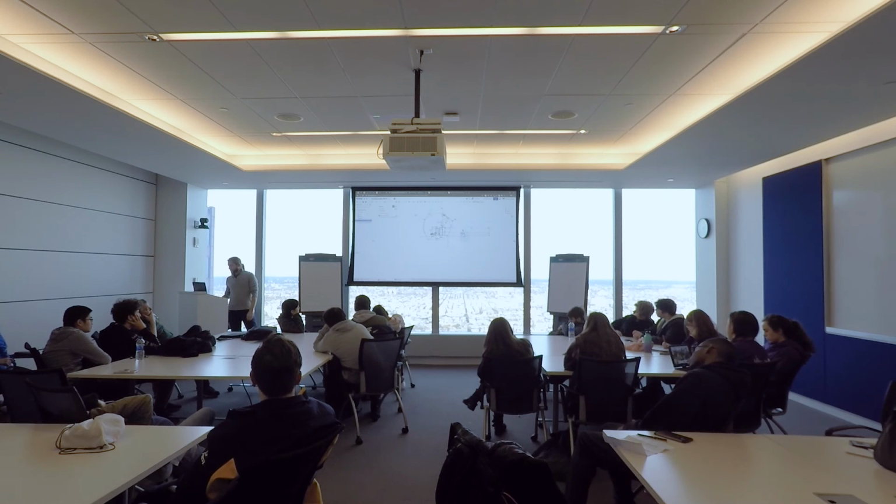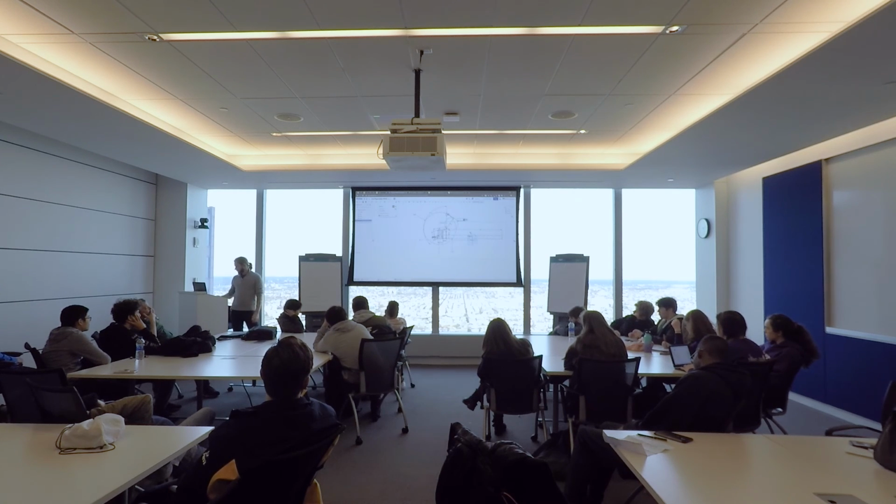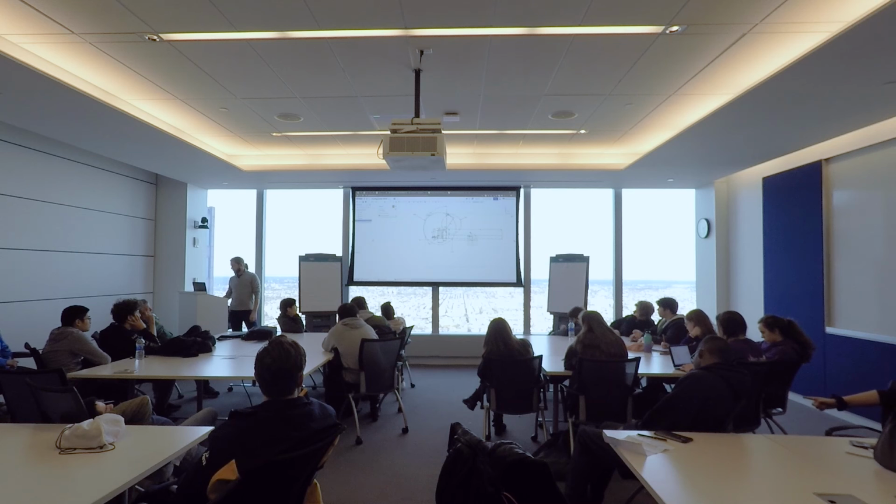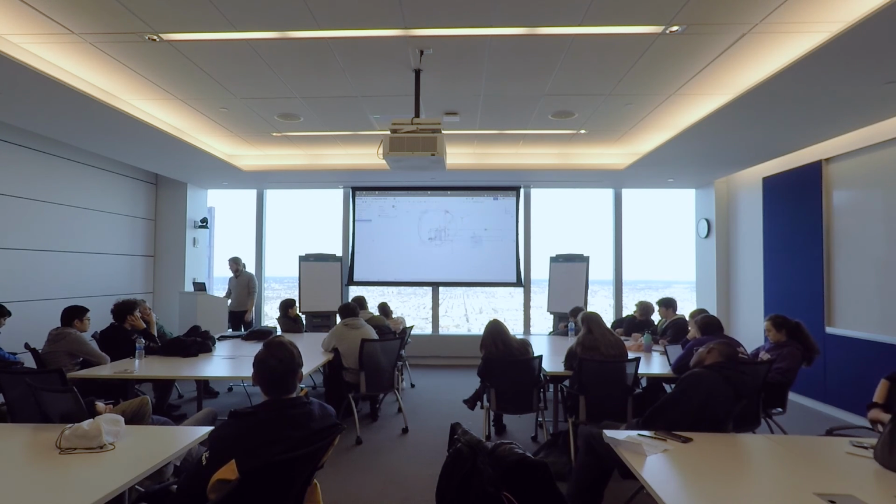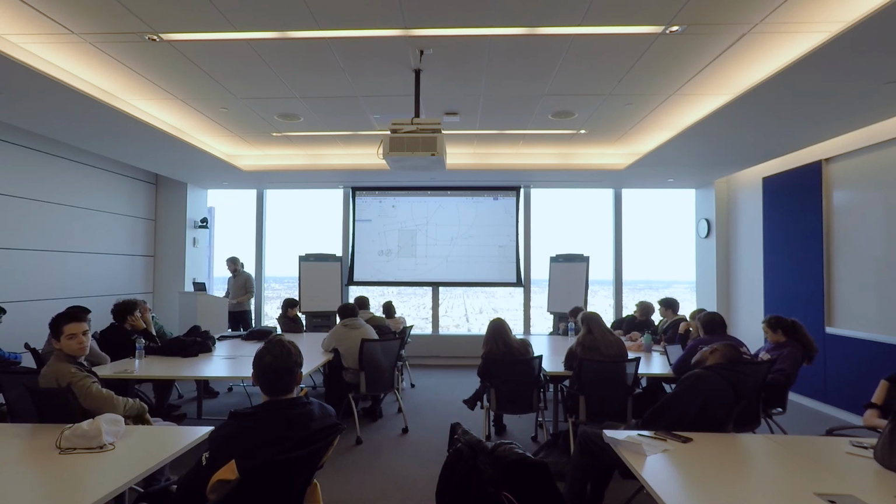And so if it's extended 10 inches, it would be retracted, I don't know, 5 inches maybe, 6? 7, yeah. 6 or 7, so this would be, we'll say 12. So now that cylinder would mount here at this point. Does that make sense? So now we can use that to make a bracket or something where the cylinder needs to be mounted.